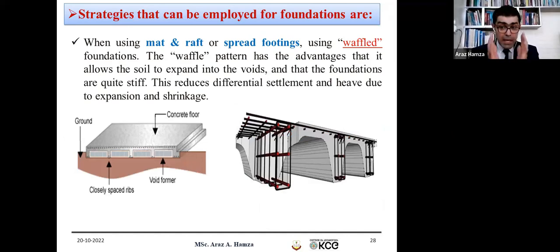Another technique that can be implemented in the foundation, most probably in the shallow foundation, is the waffle foundation. This is a new technique. It has a good response to foundation problems on expansive soil. What is the waffle foundation? If you have a combined footing, a continuous wall footing or a raft footing, you can provide a void area beneath your foundation. What is this space provided for? For the volume change of the soil.